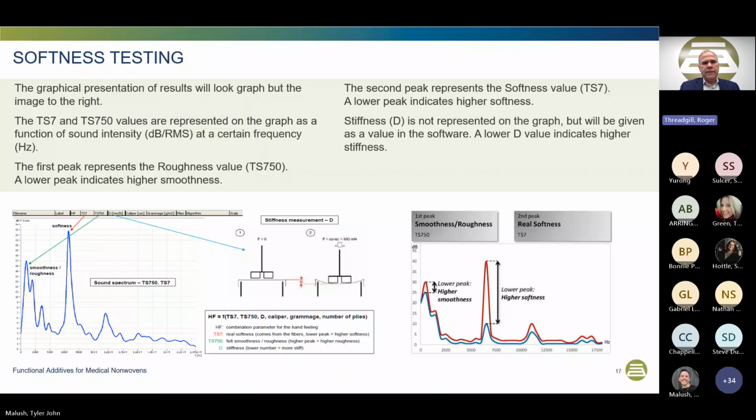And the tried and true method for evaluating softness is really human panel testing. You literally get a group of people to compare different fabrics and rate and rank them in the series of modifications to try to get a sense of, okay, well, this one's more coarse, this one's more soft, this one has a better crush and recovery. So you get your human panel to rate and rank these and compile their information together.